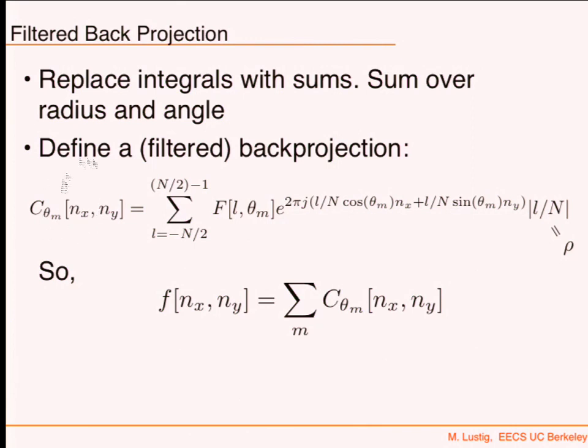And if I take all this set of signals and sum over them, that basically means I'm going to sum over thetas. If I sum over all these theta m's, then I will get myself the reconstruction. But I want to define this first, because this back projection is a very interesting operation. So this is the filtered back projection. This part over here, if I sum over the m's, then I would get the sum over the thetas, which will give me my signal. I'm repeating it many times, so it sinks in.